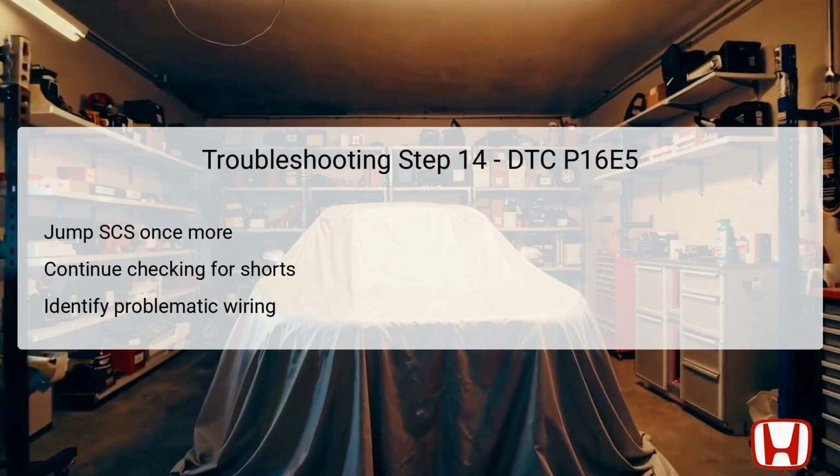Jump the SCS line using the HDS and hold off for 1 minute before proceeding with continuity checks. Disconnect connectors and proceed to methodically evaluate the continuity by removing one connector at a time, observing to see if continuity disappears when a connector is disconnected. This technique of testing helps to localize areas that may have issues in the LIN wiring system, where some wires effectively carry signals, while others may have failed.